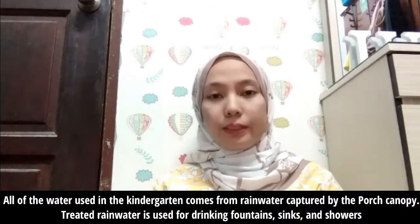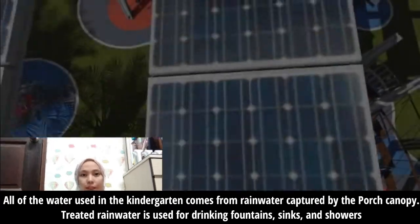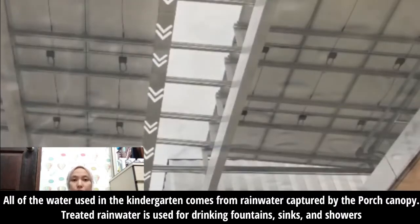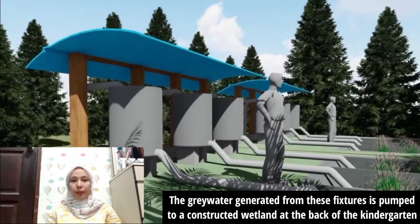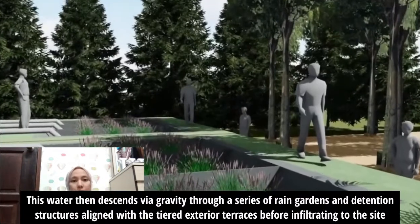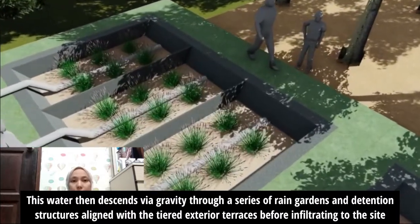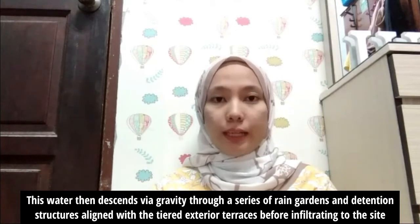All of the water used in the kindergarten comes from rainwater captured by the porch canopy. Treated rainwater is used for drinking fountains, sinks, and showers. The grey water generated from these fixtures is pumped to a constructed wetland at the back of the kindergarten. This water then descends via gravity through a series of rain gardens and detention structures aligned with the tiered exterior terrace before infiltrating the site.